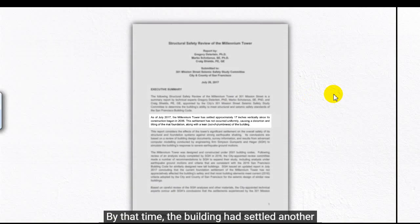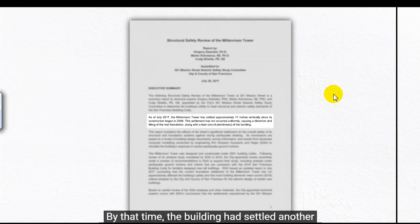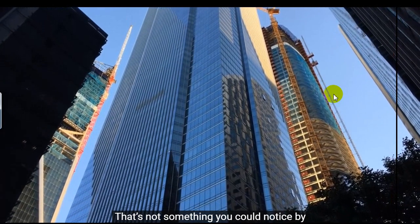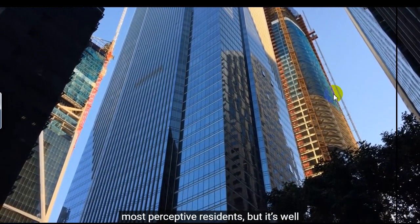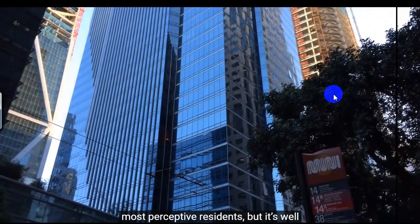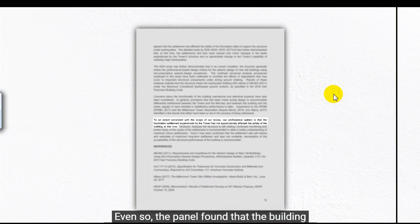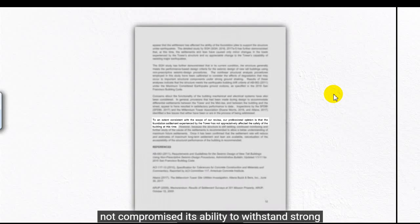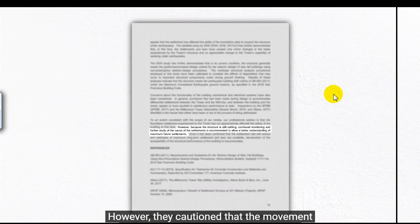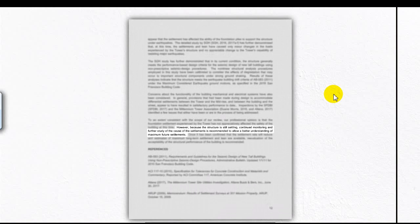By that time, the building had settled another inch and was out of plumb by more than a foot, or 30 centimeters. That's not something you could notice by eye and was probably only discernible to the most perceptive residents, but it's well beyond the 6 inches allowed by the building code. Even so, the panel found that the building was completely safe, and the settlement had not compromised its ability to withstand strong earthquakes. However, they cautioned that the movement hadn't stopped and further tilting may affect the building's safety.